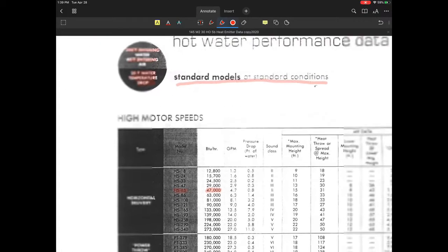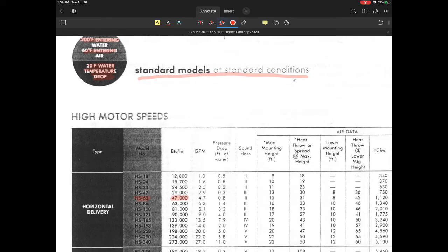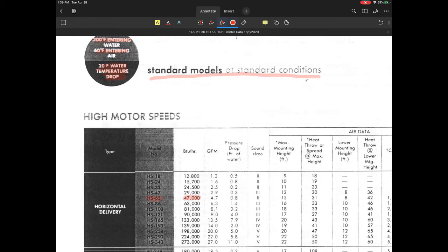Well, the same unit heaters are oftentimes used to handle both steam as well as hot water. And the steam units are utilizing latent energy by the conversion of the vaporous steam into liquid condensate, and you're going to get more BTUs out of those units. When you run water into these systems, you're going to get much less capacity out of those. You're taking 200-degree water in, you're extracting 20 degrees of sensible heat out of that water at the desired flow rate, and then of course that gives you those BTUs.